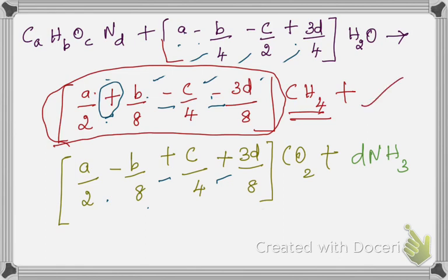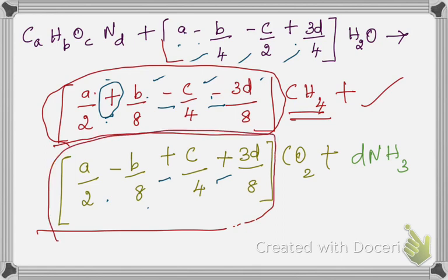Suppose they have asked, out of 1 mole of decomposable matter, how much carbon dioxide is evolved, then we have to use the corresponding empirical relationship. And likewise, if water, then we have to use the other relationship. So in one particular empirical equation, you can determine the value of methane, carbon dioxide as well as ammonia. That is, if you only determine the value of D, easily you can get the value of ammonia. Okay, now we will get the value for the methane evolved.